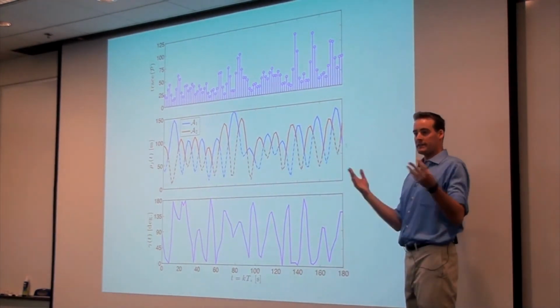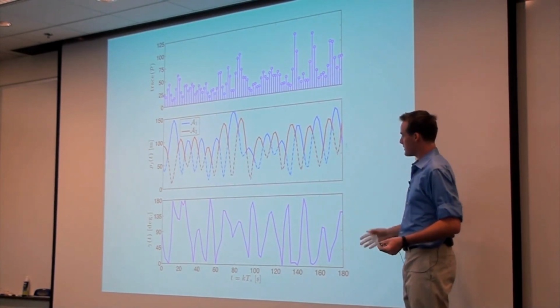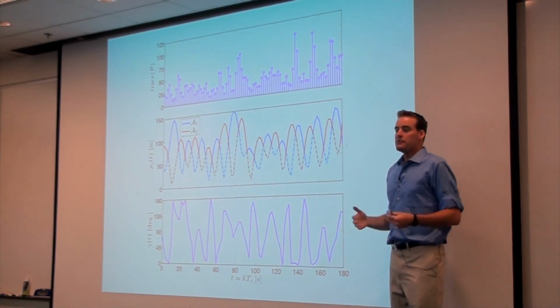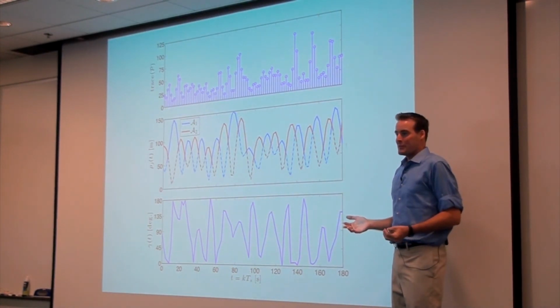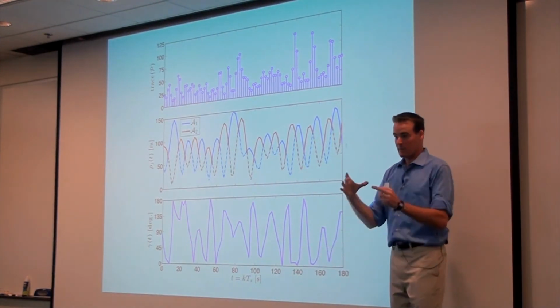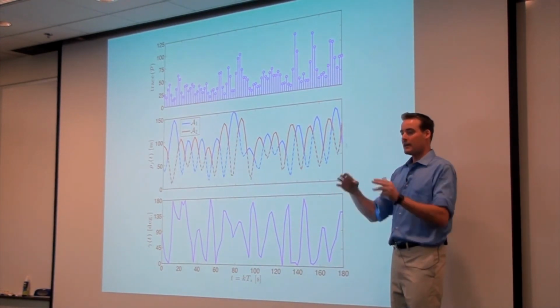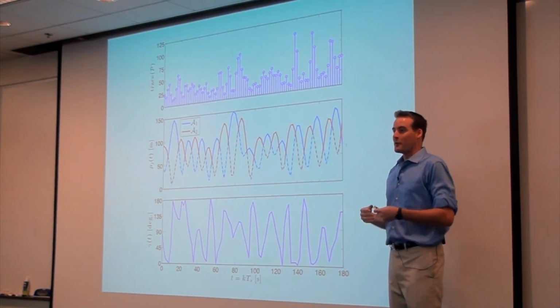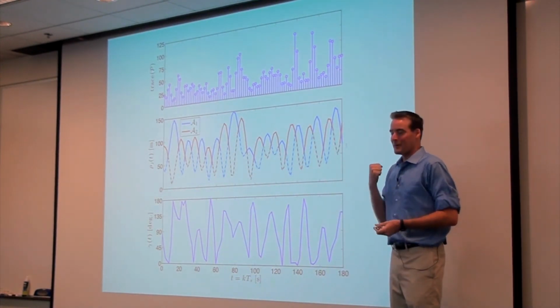And this is the big takeaway from this project that Stephen did: 90-degree standoff tracking is not the best thing that you can do. If you can spare the computational horsepower, you should be running an optimization algorithm that directly minimizes the size of the ellipse, not tries to keep them at 90 degrees. So that's another example of real-world controls engineering that is happening right now.